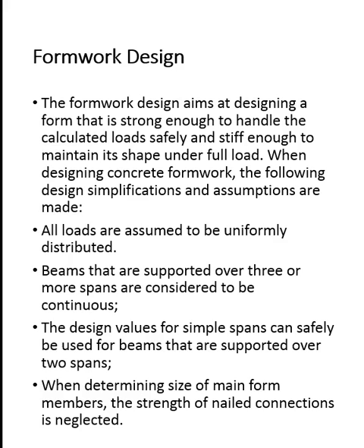Okay, again, safety, isn't it? That's all we keep saying, safety. We assume loads are uniformly distributed. Remember, that's part of the concern, especially during construction, as you're placing that concrete, the loads aren't uniformly distributed, are they? So one of the things you try to do when building and designing is manage how the loads are applied to the forms, so that you don't overload the forms and cause a collapse.